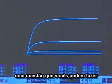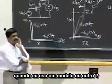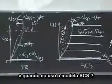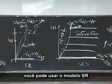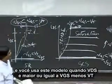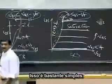Okay, so one question you may ask is, when do I use one model or the other? When do I use the SR model, and when do I use the SES model? If you want to do a real detailed analysis, then you can use the SR model when VDS is less than VGS minus VT, and you would use the other model when VDS is greater than or equal to VGS minus VT.